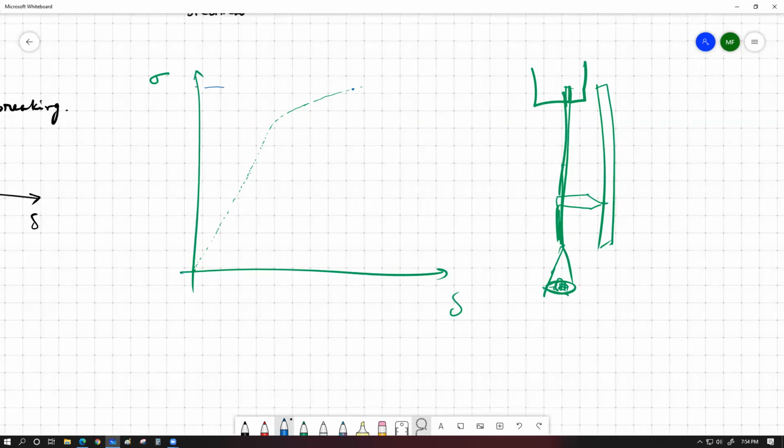The stress value is going to start to decrease from this point downwards, because whenever we reduce the F, the cross-sectional area remaining constant, the stress will become lower. So from that point, this returning graph is going to follow a track which is parallel to the original straight line part of the Young's modulus.